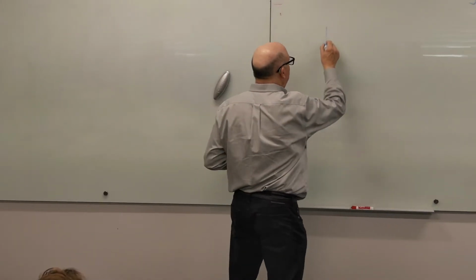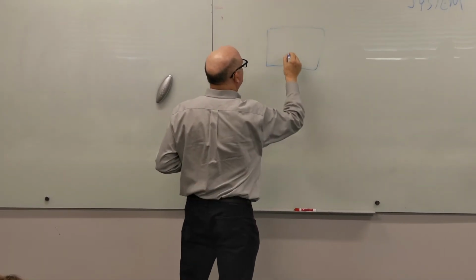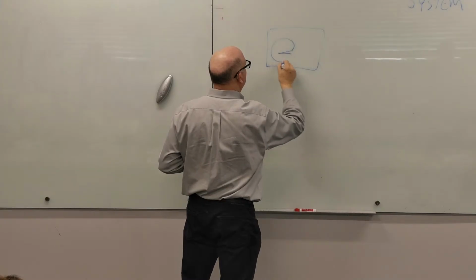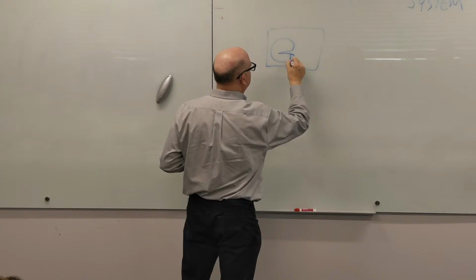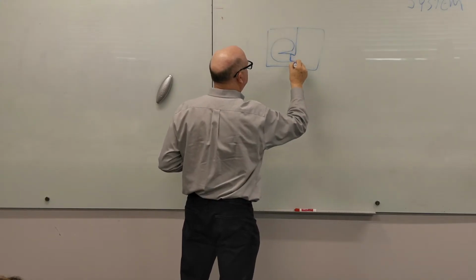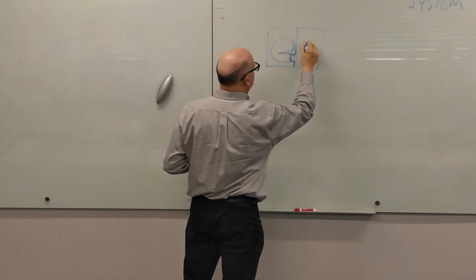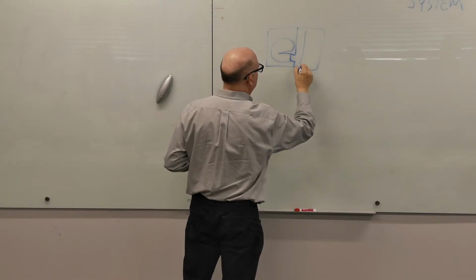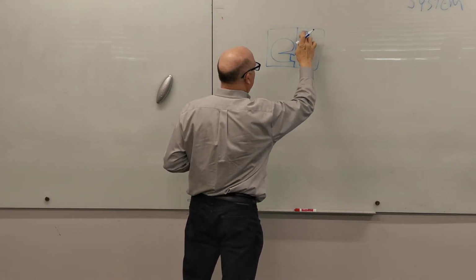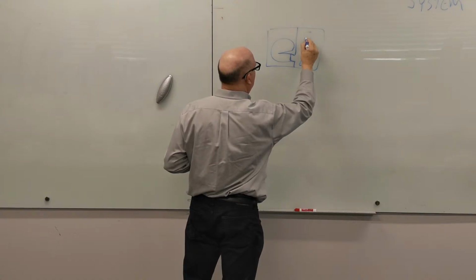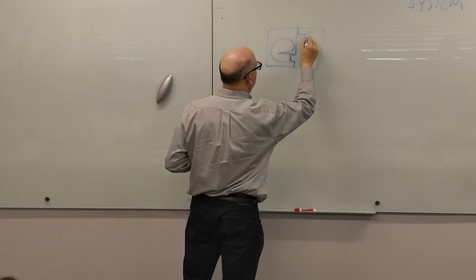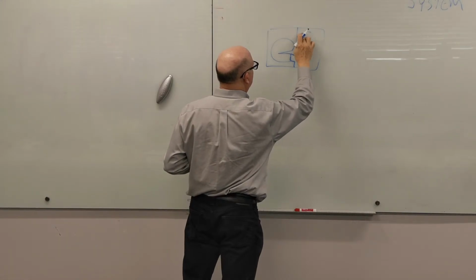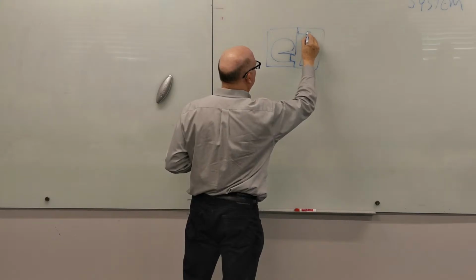So the standard dual duct air handling unit would look like this. And it would discharge with a little flex. It would discharge into the plenum. There'd be a cooling coil sitting here. And then there'd be a heating coil up here. Let me try it this way. Be a heating coil here.